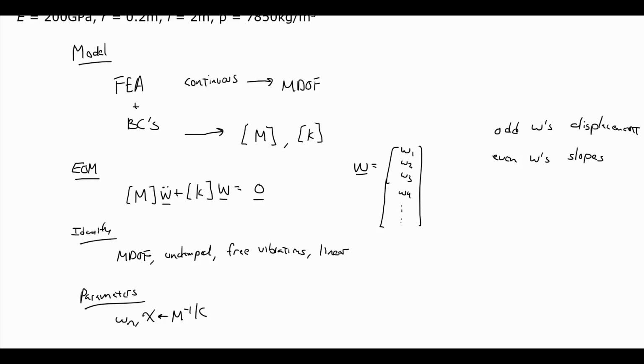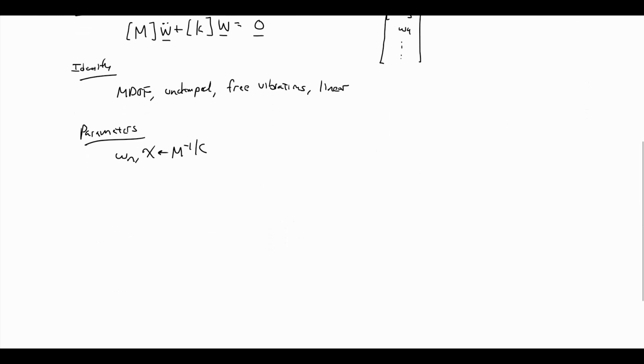So the way that our mesh is done from our shape function, the way that we put our degrees of freedom together, we are going to be solving all of the displacements and the slopes simultaneously. We're going to need to keep that in mind when we apply initial conditions, that we're applying the right initial conditions on the correct degrees of freedom. But we'll step back into this when we get to that point.